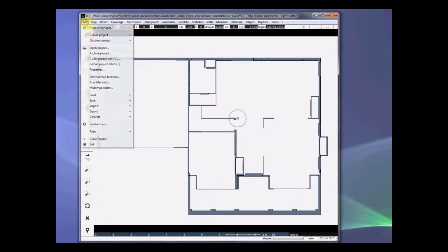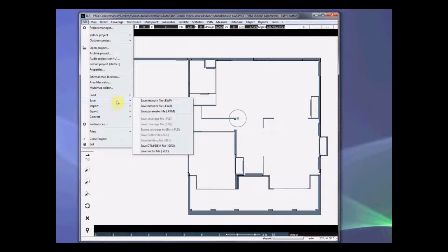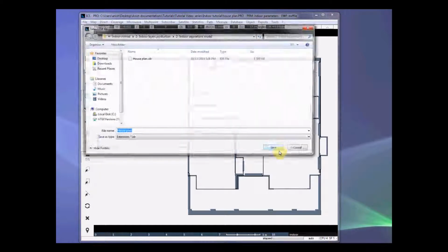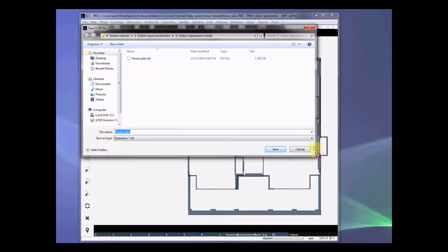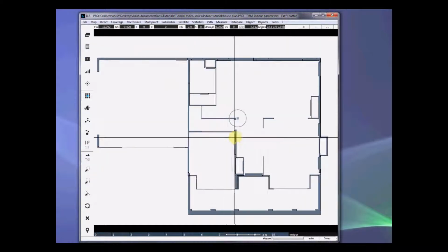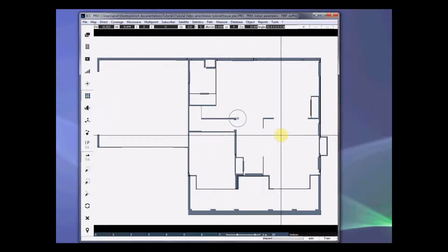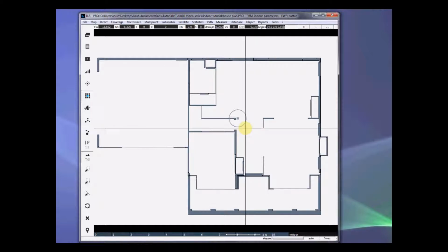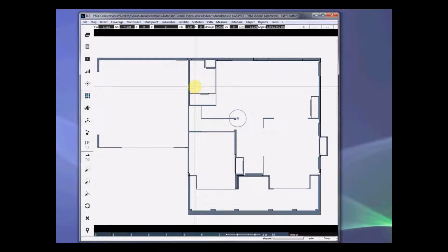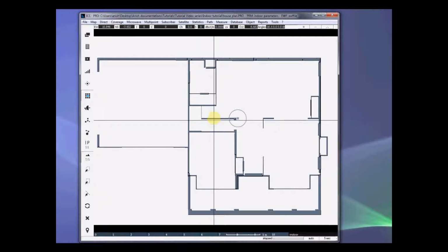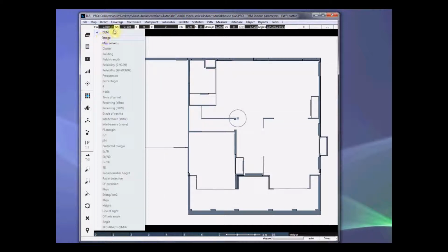And after you create all this, you need to make sure you save the DEM file, save the geo file, because there is no such thing as an undo button in this ATDI software. So if you make a mistake, you'd have to redo it again or figure out another way to remove it. And hence, what we strongly recommend is that at every step of the drawing that you make, you save your DEM files.